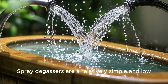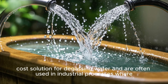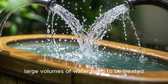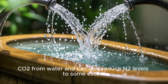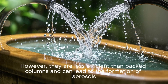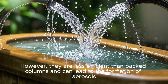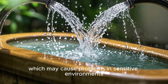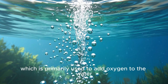Spray degassers are a relatively simple and low-cost solution for degassing water and are often used in industrial processes where large volumes of water need to be treated. They are particularly effective at removing CO2 from water and can also reduce N2 levels to some extent. However, they are less efficient than packed columns and can lead to the formation of aerosols, which may cause problems in sensitive environments.